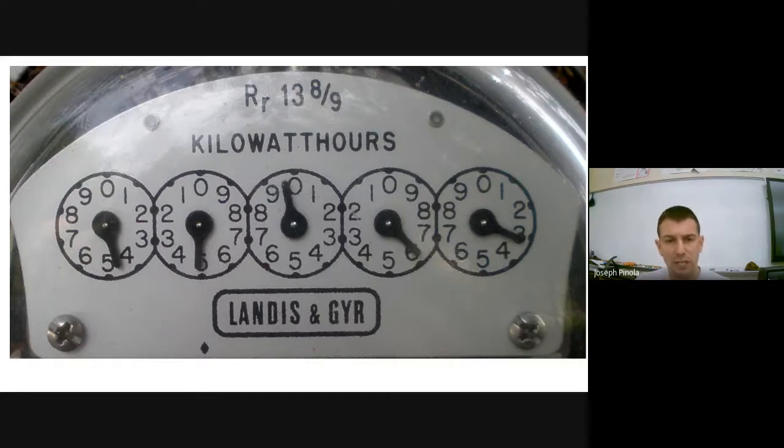So what does this dial read in front of us? The first digit would be a 4. And I'll write that big on my board here. That's because going clockwise, the dial goes past the 4, but not quite up to the 5. Notice the second dial. A lot of people would be tempted to say that it should read 5 because it goes slightly past the 5. But we have to read it from the other direction, increasing our numbers. So reading the second dial counterclockwise, we can see that it comes out to a second digit of 4, because it is between 4 and 5, and we take the lower number.